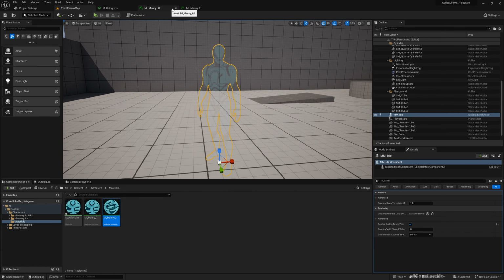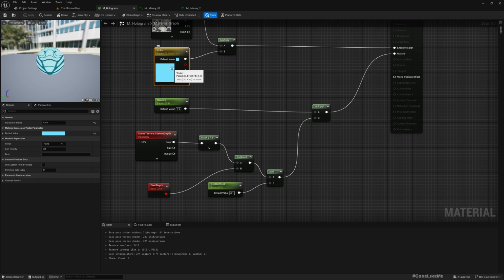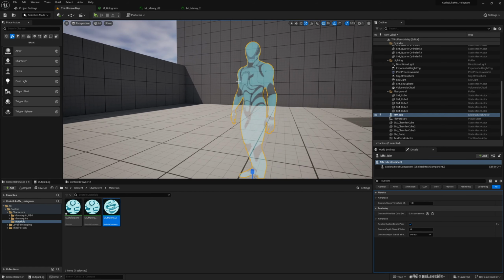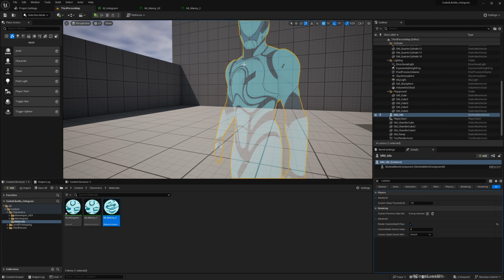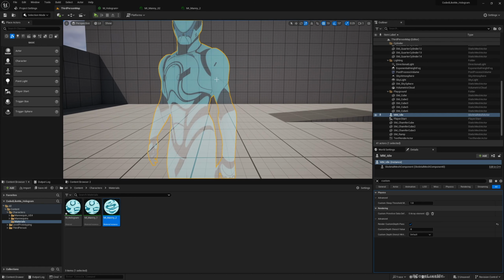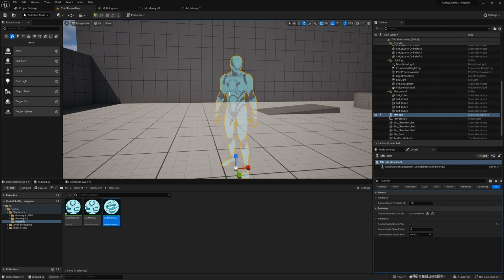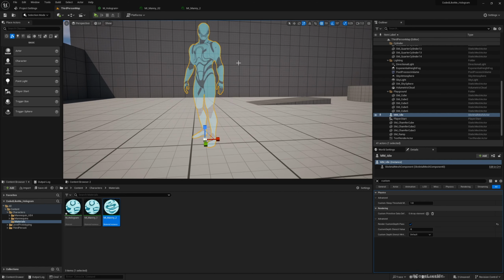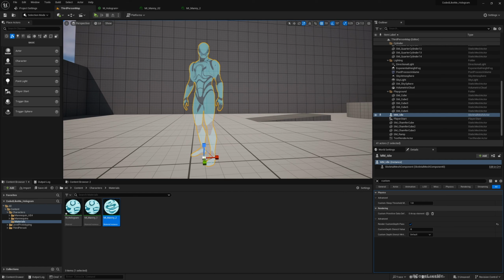Nice. Now if I increase the luminosity of this, I should get a better rendering. Yeah, see, now we have the transparency and we don't have these inside faces rendering, so we have a clear picture. All right, great. Now we have the basic. The next step is, let's make it look more like a holographic material. So the first thing I would try is I want to fade out this lower part